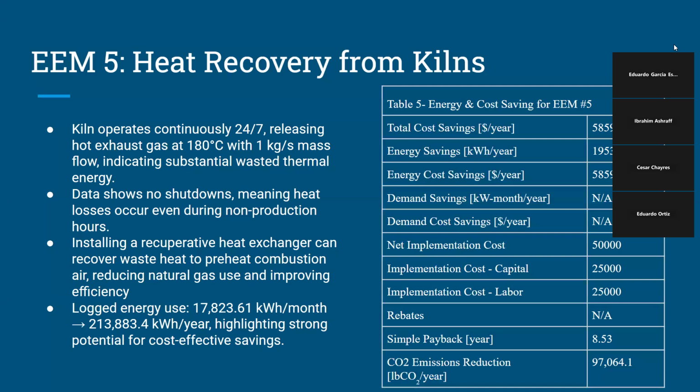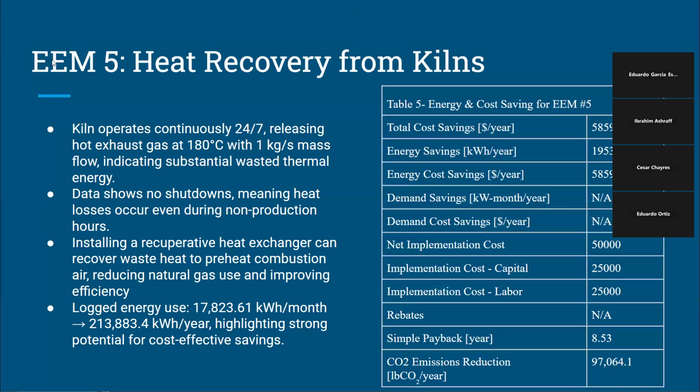Our energy savings in kilowatt hours per year are around 195,300. And our implementation cost was $50,000. And for capital and labor, it was $25,000 each. Our simple payback would be 8.53 years.